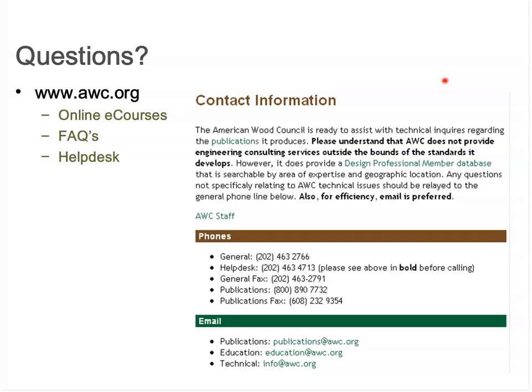The gun nails or pneumatic nails are all covered in evaluation reports. The old legacy report, I believe, was NER 272. If you go to the website for the International Staple and Nail Tool Association, I believe their website is ISANTA, I as in India, isanta.org, you can get copies of the legacy report, NER 272, and whatever the newer national evaluation report is for pneumatic nails.